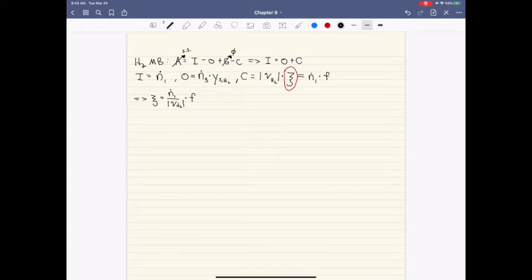Right? And so we can rearrange the equation so that we say that the extent of reaction is just equal to this relationship. And if we plug in all the values, well, actually, this consumption term here should be the ν dot in order for the units to be consistent, since we're dealing with an open system.